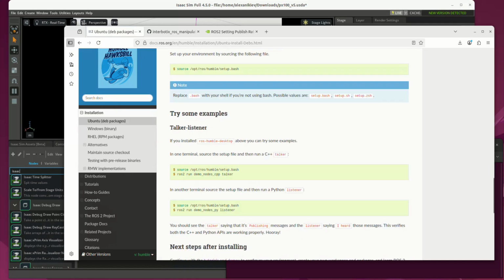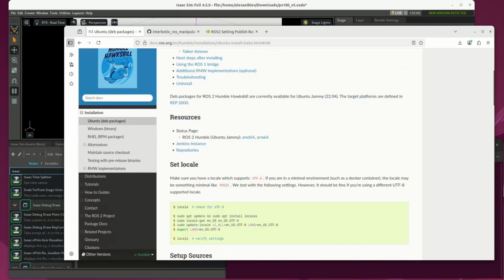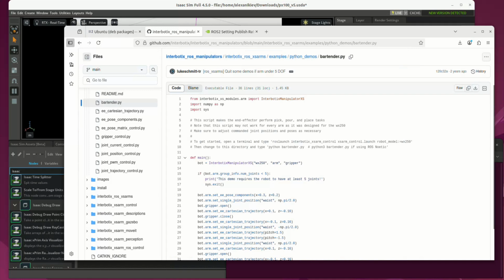So first of all, we're looking at the Sim host right now, and we have Ubuntu 22 LTS installed there, and we'll install ROS2 Humble. And this is the installation procedure, which is a vanilla installation procedure available on the website. And then, as we start using the terminal, we don't want to forget sourcing the ROS2 environment.